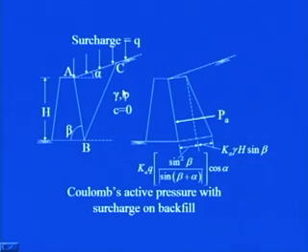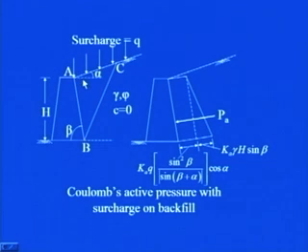How does it take into account? You can see here that the backfill is cohesionless material, that is c is equal to 0, it has unit weight gamma, and angle of internal friction equal to phi. Then there is the surcharge Q. As you have seen, how we calculate lateral earth pressure is that we calculate the vertical stress at any particular level, multiply that by the coefficient of earth pressure and simply get the lateral earth pressure. So, in exactly the similar manner, since it is inclined, if it would have been the horizontal one, then we would have simply said K into Q.